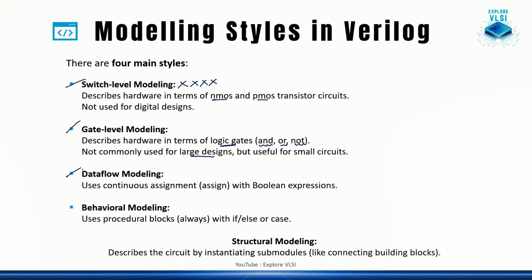Then comes dataflow modeling. In dataflow modeling, we have Boolean expressions. By looking at the expressions, we can directly use the assign keyword and write the Verilog code. But here also, getting all the Boolean expressions for complex designs is impossible. That's why we go for behavioral modeling.